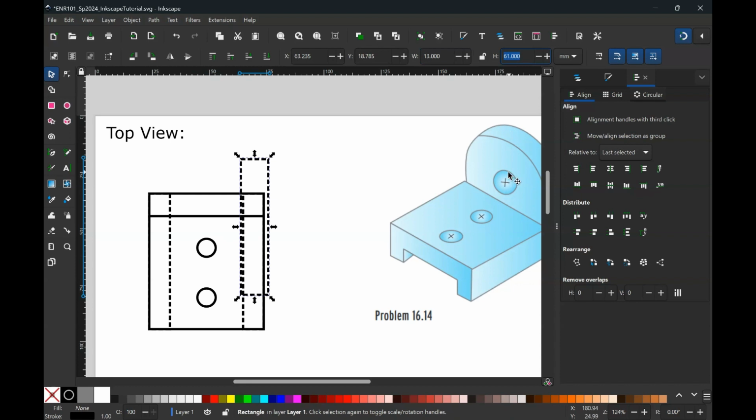And we notice that this hole isn't completely dug all the way through. It's still sort of showing this colored section here. So we're going to make it only a partial hole, which is an important feature to note from this top view projection. And we're going to make it go through half of that distance, so 6 millimeters or so, aligning once again to the bottom portion there.